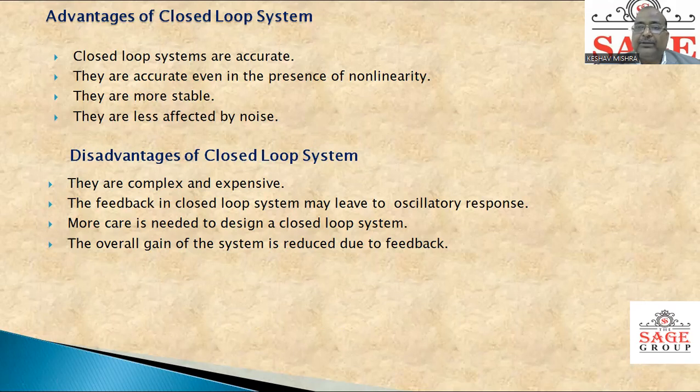As I have quoted the example of the amplifier, stability is required, but it is at the cost of reduced gain, because the overall gain with feedback in an amplifier is the basic amplifier gain divided by some factor. We will discuss in coming classes how the closed feedback system can reduce the gain, but stability we can achieve.